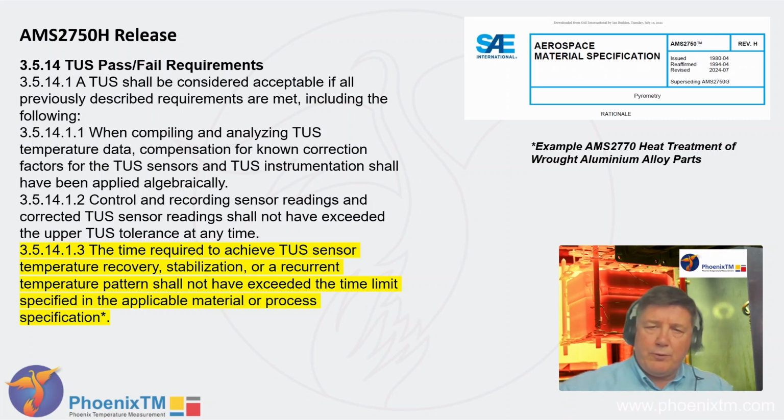any temperature uniformity survey. The TUS pass-fail requirements, as you can see on the screen at the moment, are very clear and concise. But it's important to remember that on some occasions you need to combine the specific requirements of the AMS2750 with other associated standards that may be relevant to the material or the processing that you're performing.